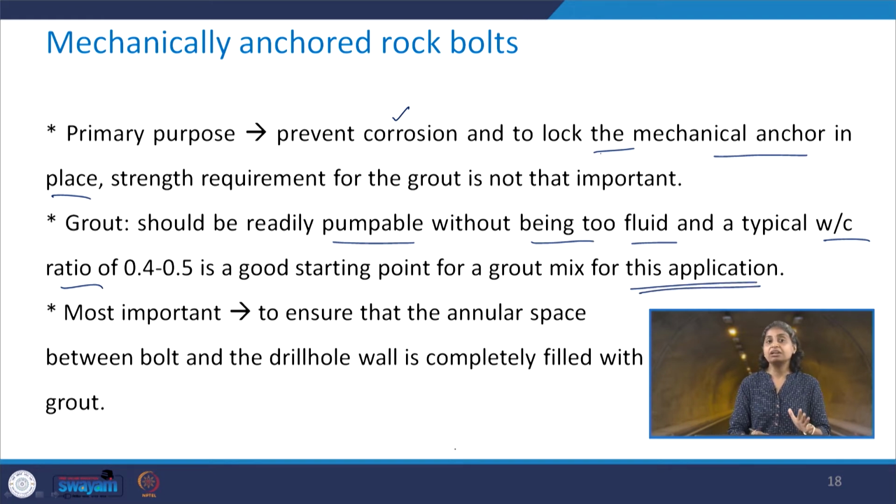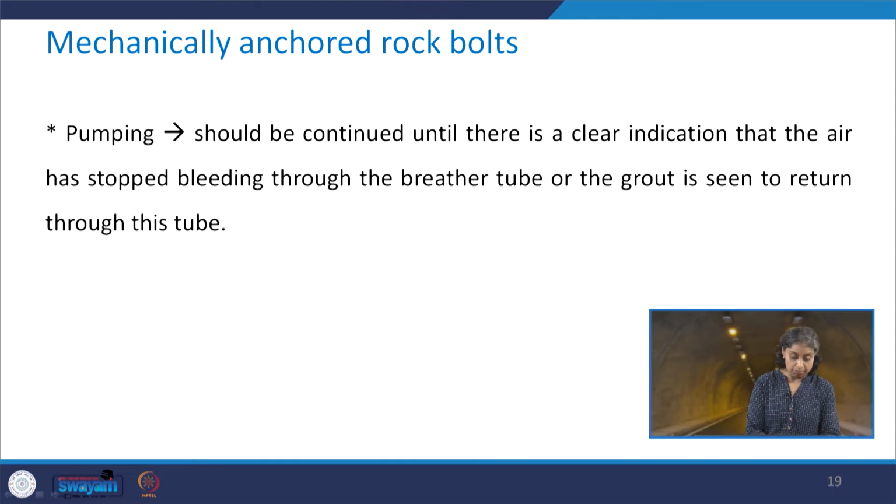The most important thing to note here is that one needs to ensure that the annular space between the bolt and the drill hole wall is completely filled with grout, because if it is not, then we will not be able to derive the maximum benefit of the installation of the rock bolts.